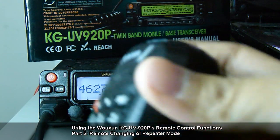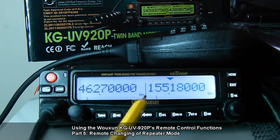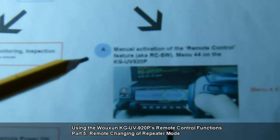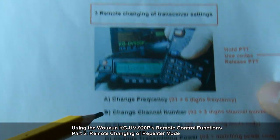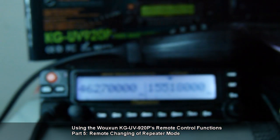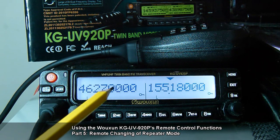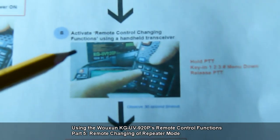Then the KG-UV920P would reboot, this time with both VFOs locked as indicated by this icon. Now that we have done procedure A, we can now proceed to procedure 3C, but only after we have done procedure B. So if, for example, we would like to shift from normal communication mode to directional crossband repeater mode, you do procedure B followed by what?